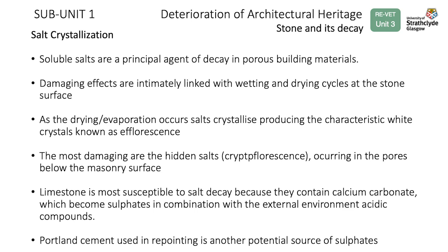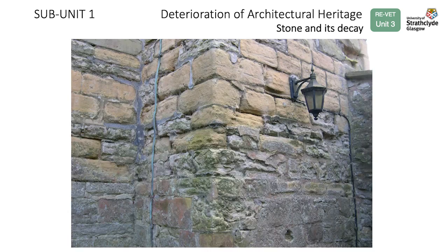Salt decay is more likely in limestone because it contains calcium carbonate, which becomes sulfates in combination with external environment acid compounds. Portland cement used in repointing is another potential source of sulfates.